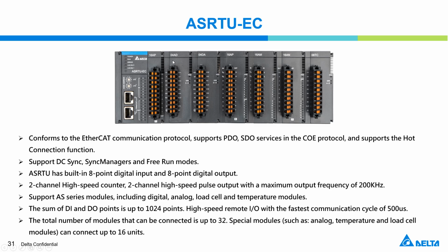The advantage of the analog input module is that, unlike the R1-C, the first module I introduced, here you can use the software to choose different analog signal types for different channels. The R1-C software only allows you to choose the same analog signal for the four channels.